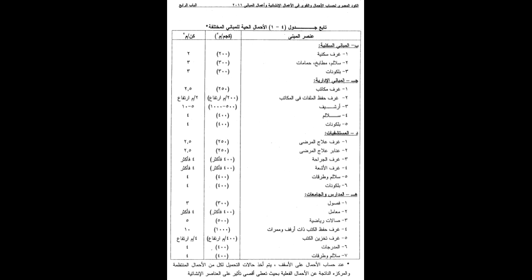The files also have less paper, so it is not too much. But if you have an archive full of paper and the paper is heavy, the archive could take loads of 500 to 1000 kilogram per square meter. Stairs in the administration buildings, 400 kilogram per square meter, because they have more load than residential buildings. People go up and down. In balconies also 400 kilogram per square meter.